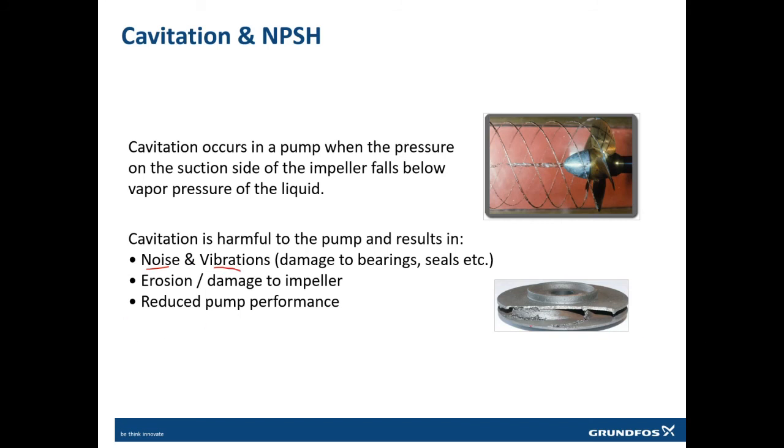And what will happen? The result of this erosion is that your impeller will be badly damaged because of this cavitation. And secondly, reduced performance. Your pump performance will be reduced drastically. How drastically? You remember, this is how the pump curve looks, but after cavitation your pump curve will look something like this, or even worse than this. So cavitation is a major concern in pumping systems. We'll talk about what cavitation is, how it happens, and how we can stop it.